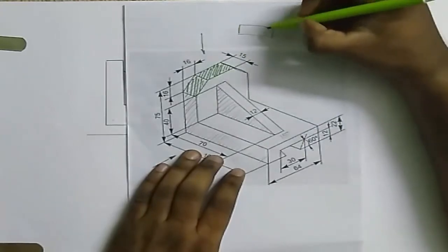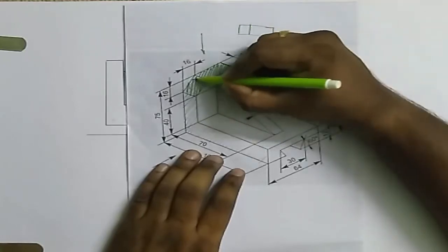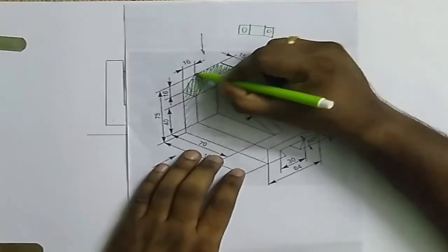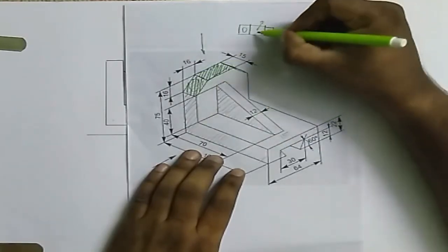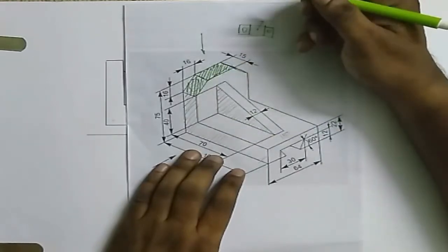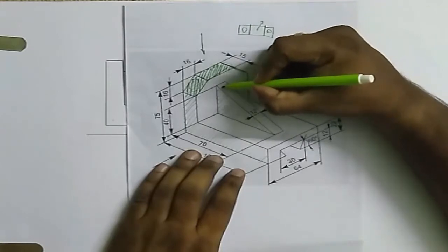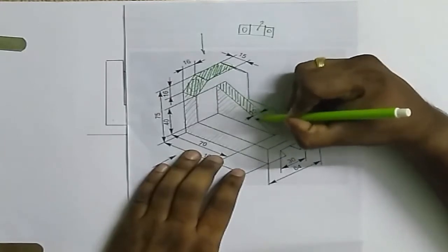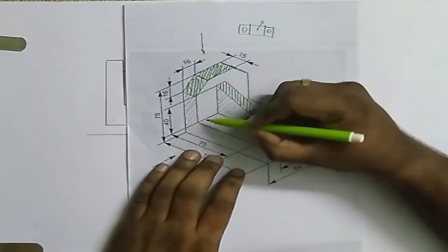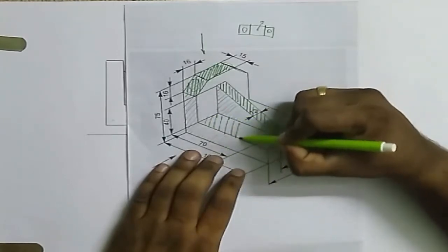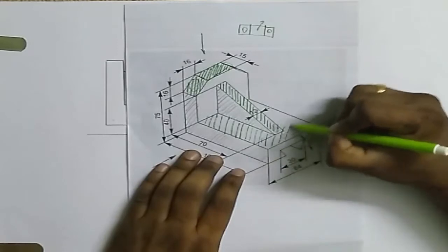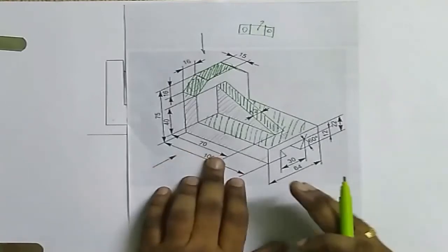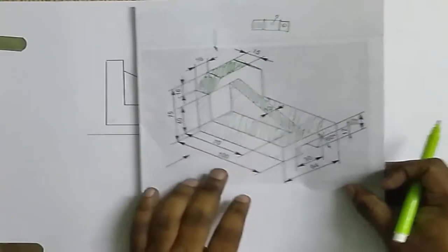So like this you will get a surface in the top view, and this is your angled surface, and this angled surface will come here. So this rectangle is, this one is that rectangle. Okay, now similarly this face will be viewed from the top. This surface will be viewed from the top. Similarly, this surface will be viewed from the top. Okay. So I have to transfer all these surfaces to orthographic projection.